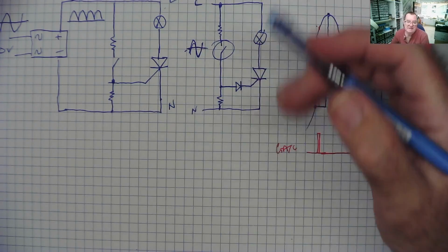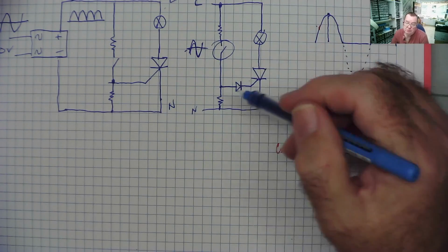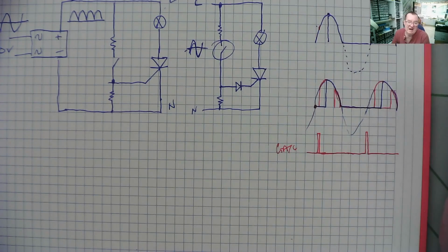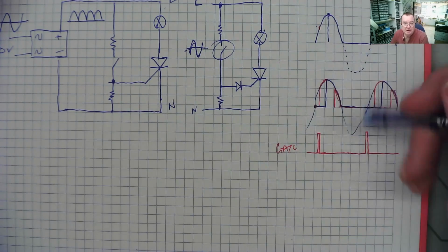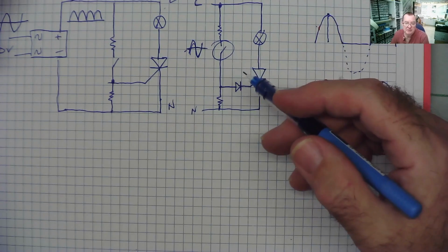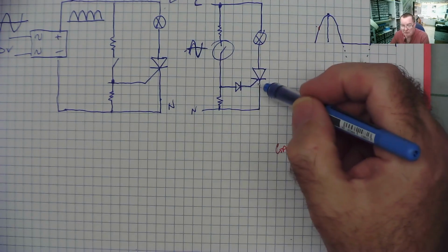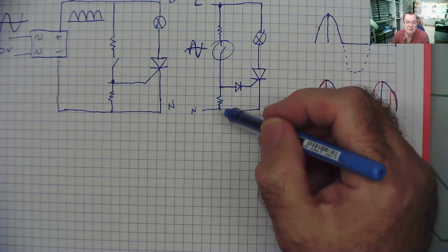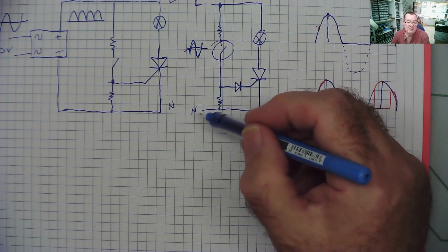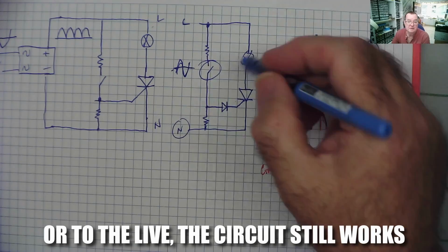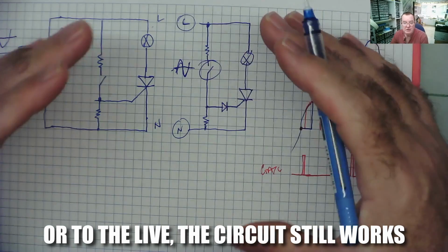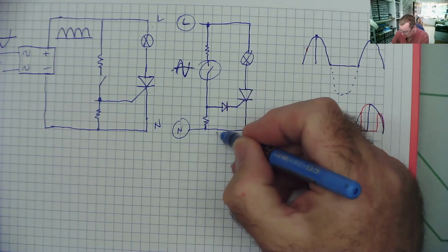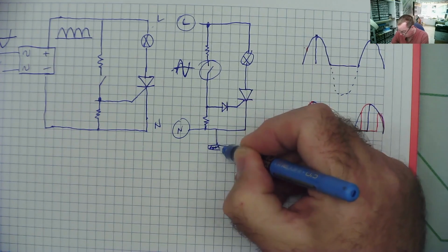As you can see then, it is easy to control a thyristor to effectively control the voltage output to the load, or at least the average voltage to the load. But there's an important thing you probably do realise about this circuit, and that is that when you apply the voltage to the gate, it's with reference to the cathode, and the cathode is connected to the neutral of your mains, and the other end, by the way, is connected to the live. So the thyristor is part of the high voltage circuit, the live circuit. This, if you like, is hot ground.